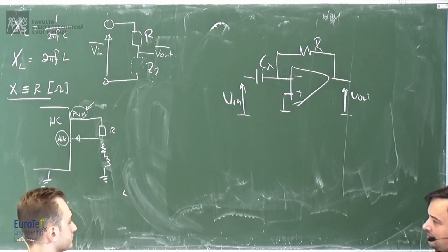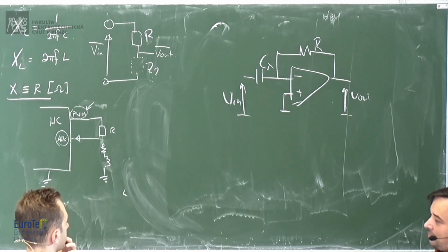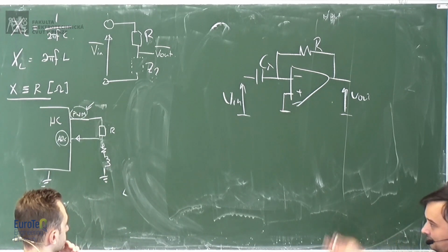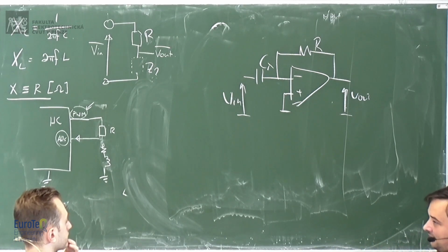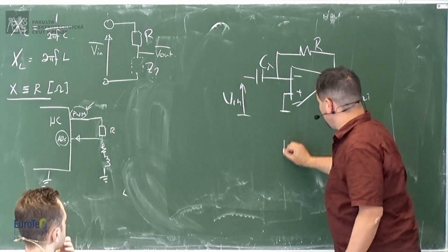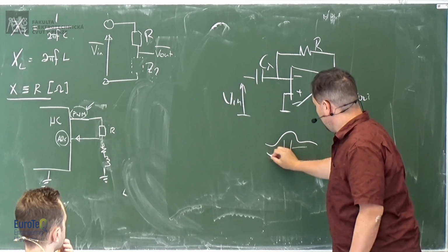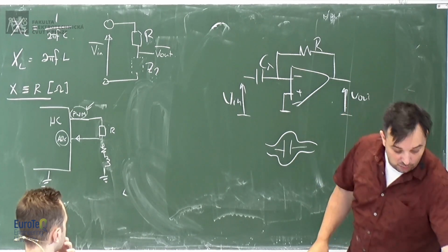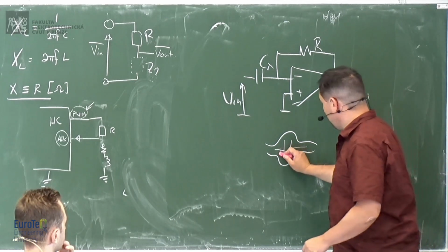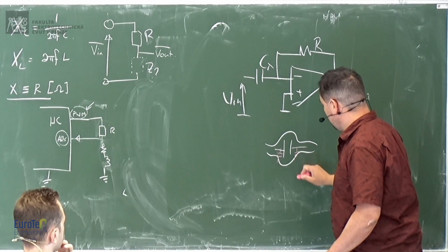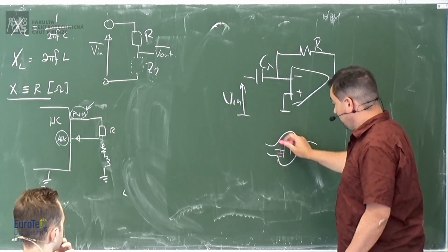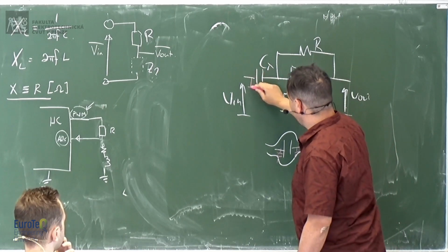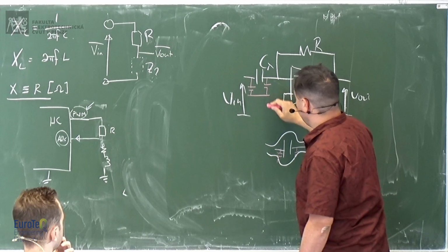But you want to measure only impedance, right? You don't care about capacitance. Now, the problem of capacitance is that they always have these parasitic capacitances and so on. So one thing you can do is to shield your capacitance. Just imagine that you have your capacitance, and you shield it with some conductive material, whatever is conductive. What you develop then is a sort of parasitic capacitance between each electrode of the capacitor and the shield. So here you will have a shield and you have some parasitic capacitance to the shield.